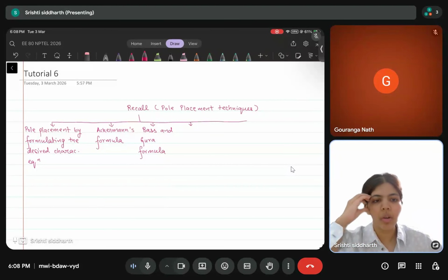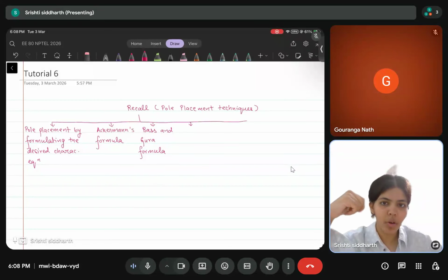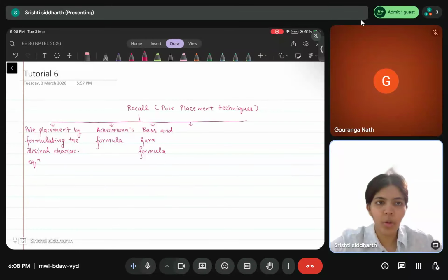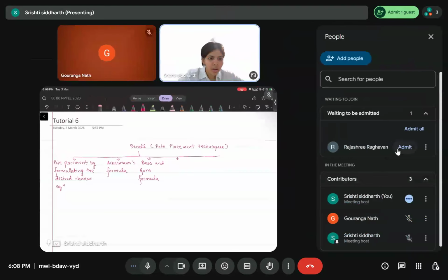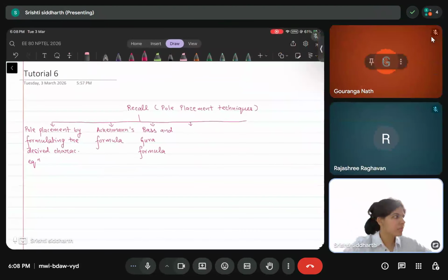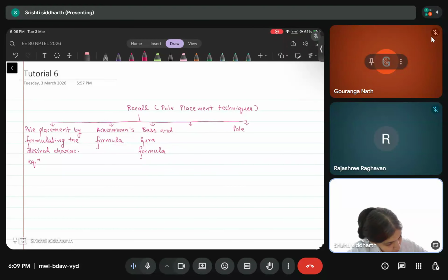Then, if the system is not completely controllable, then we can transform it into a standard form for uncontrollable systems and then design the pole placement control. In that case, the unstable eigenvalue should be stabilizable, right? So this is pole placement for stabilizable systems.